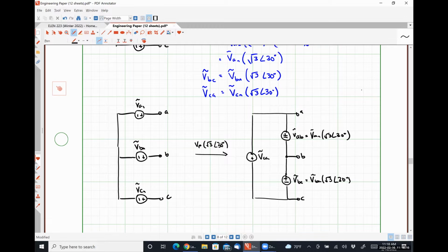That's not really our problem then. What we need to do now is figure out how to convert our phase voltages, which happen to be line voltages, for our delta connected source to an equivalent Y voltage. Any thoughts? It's the obvious answer. Yeah, divide by that exact same conversion factor. That is it.